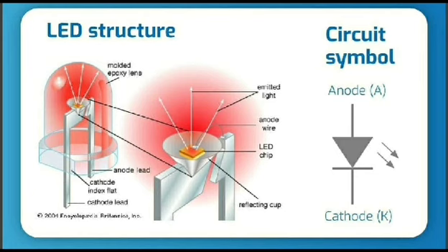Hence, during recombination of electrons and holes, that is, migration of electrons from the conduction band to the valence band, the momentum of electrons would be changed. The energy originating from these electrons will be mostly utilized for the electron momentum.